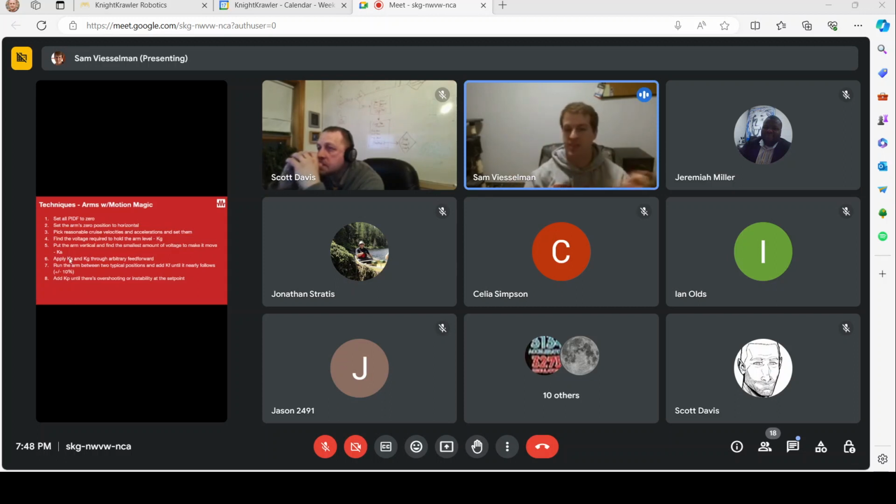Because we've canceled gravity and friction already, we should be able to tune this KF in and move our arm between two positions. And it should pretty much get to those two positions plus or minus about 10%.